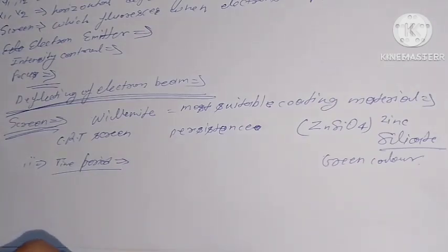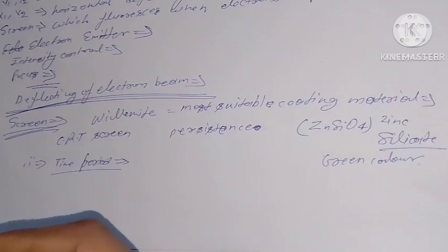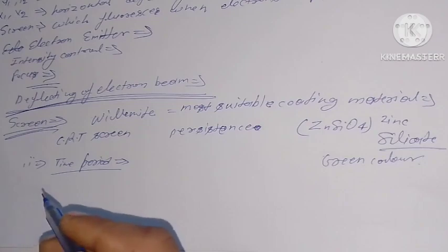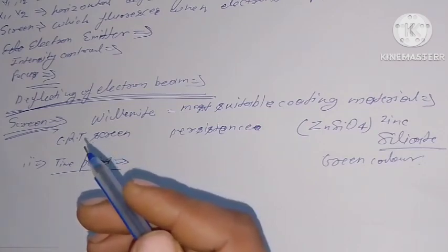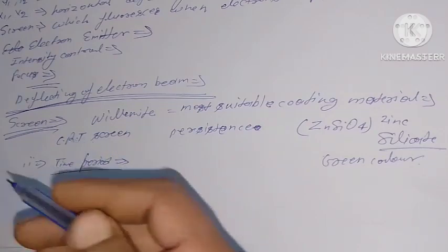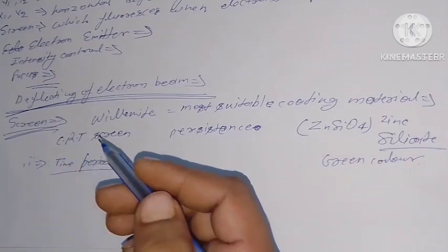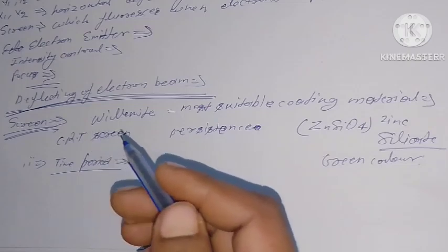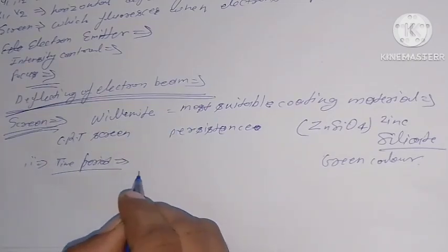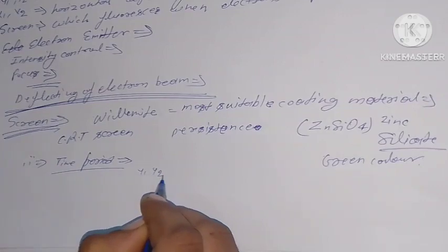One of the great advantages of a cathode ray oscilloscope is its ability to indicate very short time intervals and to record variations of voltage with time. If an alternating potential difference is applied to the plates Y1, Y2, the spot on the screen will trace out a vertical line.